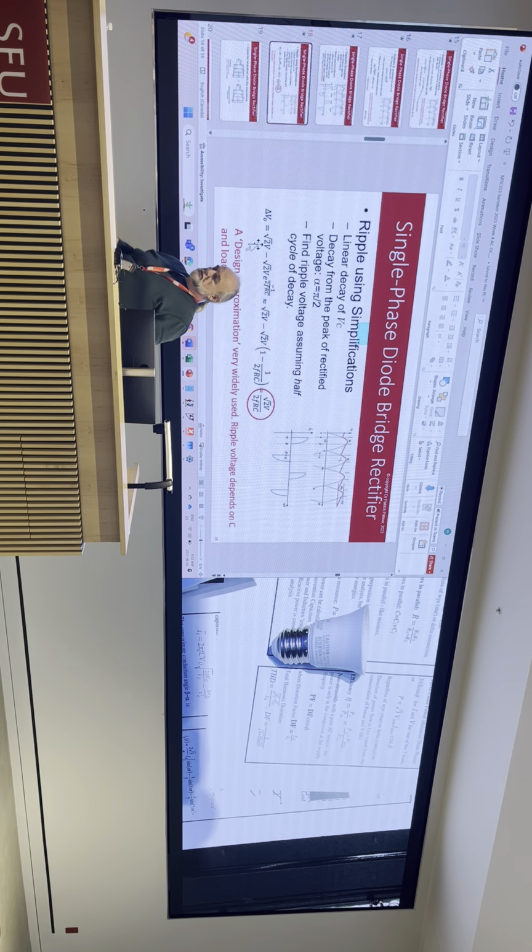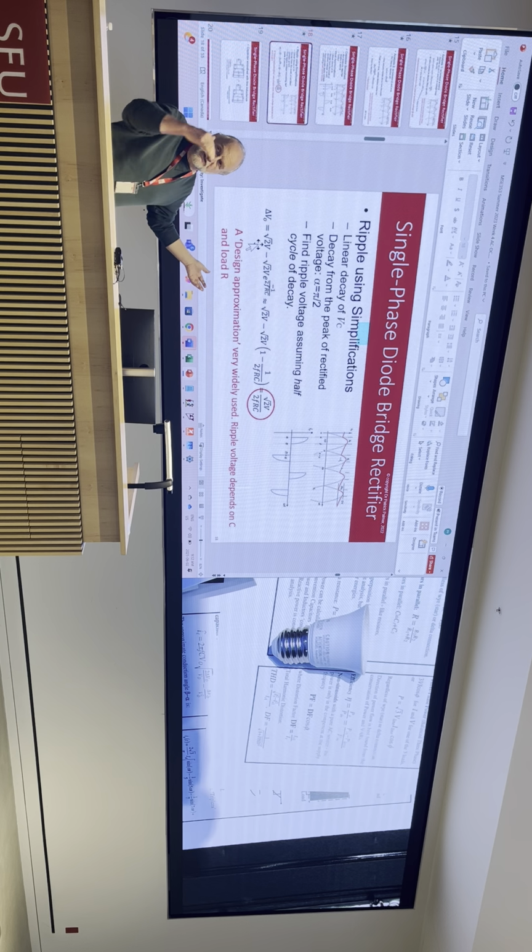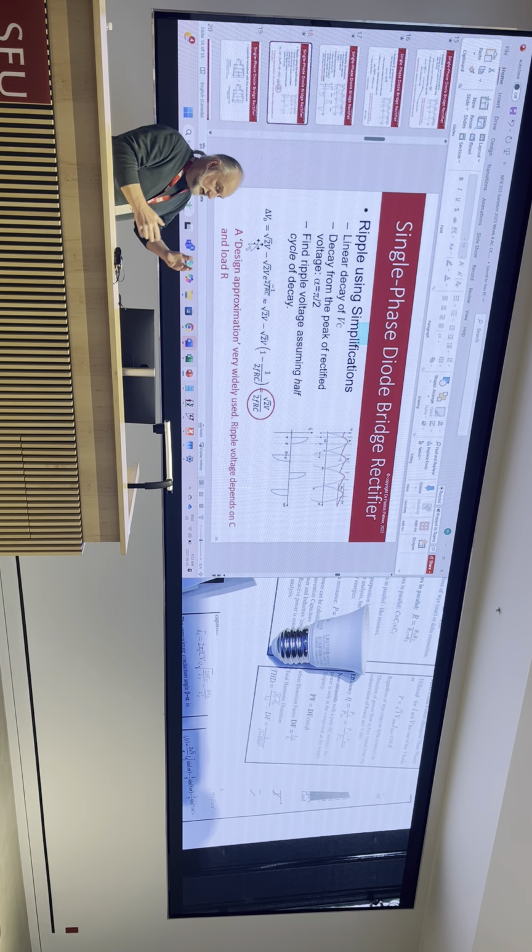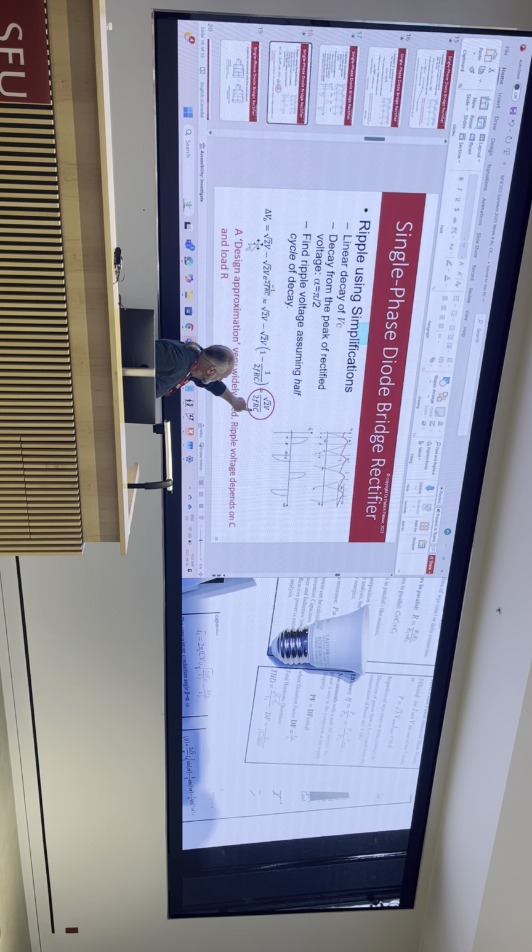That gets you most of the way to your sort of initial design, and then you can start to embellish on that and sort of say, well, actually, maybe we should use this chip, because at the moment we're using a big capacitor to get a nice light out of this thing. Maybe we should let it ripple more, in which case a small capacitor means more ripple. So we could let it ripple a bit more, but then we can use this chip. So now I'm saving money on a capacitor, and I'm spending money on a chip. Why is that possibly a good idea?